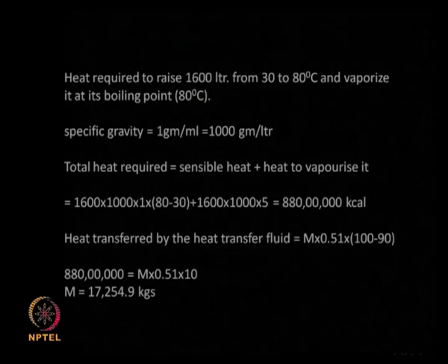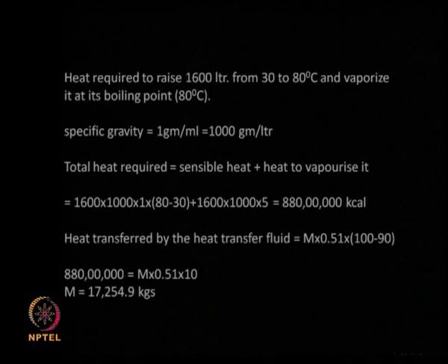So just like heating a fluid, we can also look at cooling a fluid using cooling water, same approach. You put in the heat balance for the heat lost by the hot fluid and then equate it to the heat gained by the cold fluid. So it is a typical heat balance calculation. Let us look at another problem.